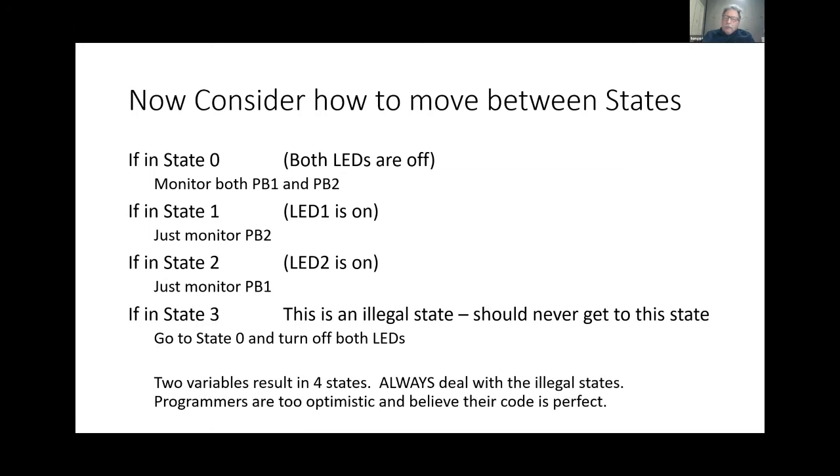Well, what happens if I got myself into state 3? Both LEDs came on. No idea how I got there, but just in case I get there, I say, okay, I've made a decision here. I'm going to go back to state 0. I'm going to turn off both LEDs. Now, I could do anything there. I could go to either state.